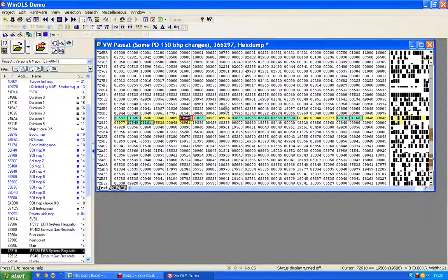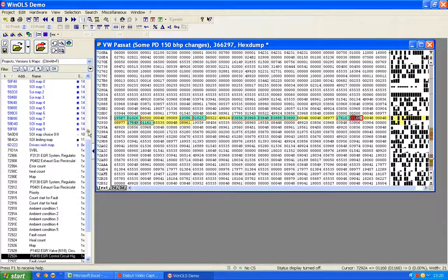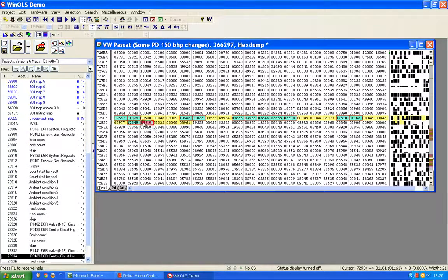So they are in pairs, and I've got 1, 2, 3, 4, ignore that, 5, 6, 7, 8. If you watch the previous videos, you will know that 8 is quite normal. The maximum number of codes for a fault path is 8. So I've got 8 possible codes and they're all being used. In one of the previous examples I showed 8 arranged in a nice line in a row, so they were easy to find, and only 2 were being used.